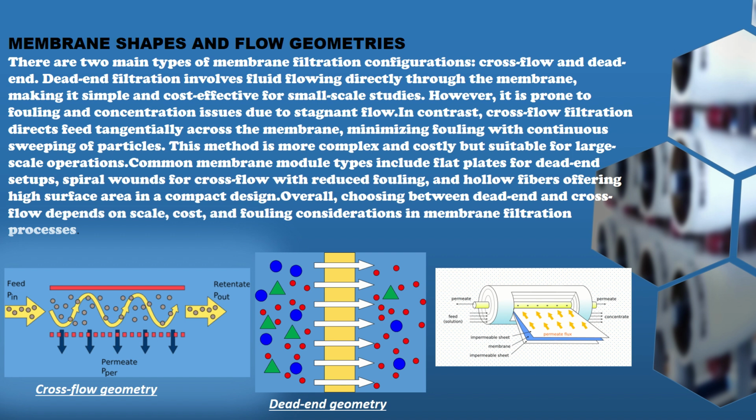Overall, choosing between dead end and cross flow depends on scale, cost, and fouling considerations in membrane filtration. But I think I will go for the cross flow, because taking the cost into consideration, I'll go in for the cross flow. So let's move on.